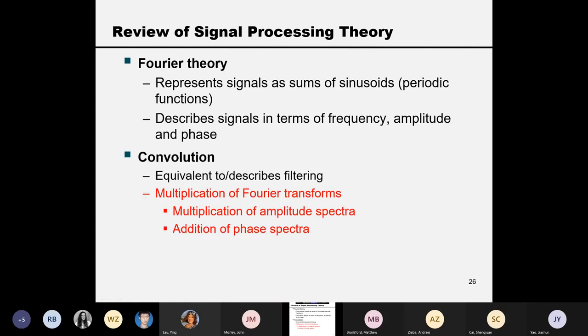Why we said Fourier transform is a fundamental theory is because it simplifies not only our explanation, but it also simplifies our life. For example, when we're talking about convolution, I already had difficulty explaining how the superposition becomes a convolution. That's really difficult. And even when you do the calculation, it will be even more complicated. So it's better to use Fourier theory. You transform this into the sine, cosine functions, and they have constant amplitude, constant frequency, constant phase, and then you can do the simple calculation.